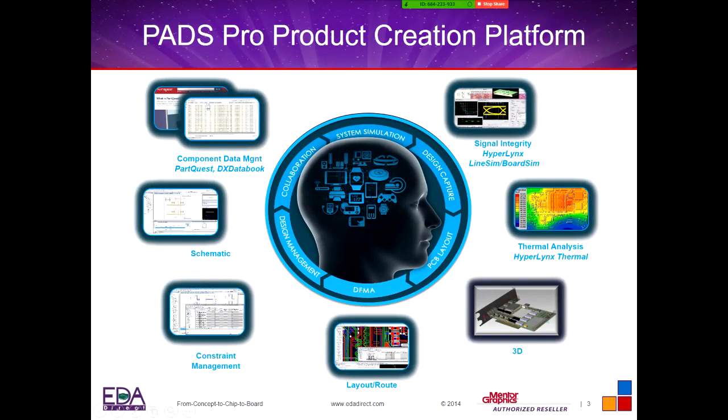And then you'll also have some of the HyperLynx tools. So you'll have thermal analysis, and you'll also have signal integrity pre and post, so that engineers can actually create models inside of HyperLynx, simulate those models to find out if they've got timing issues, impedance issues, as well as after the board's been laid out.